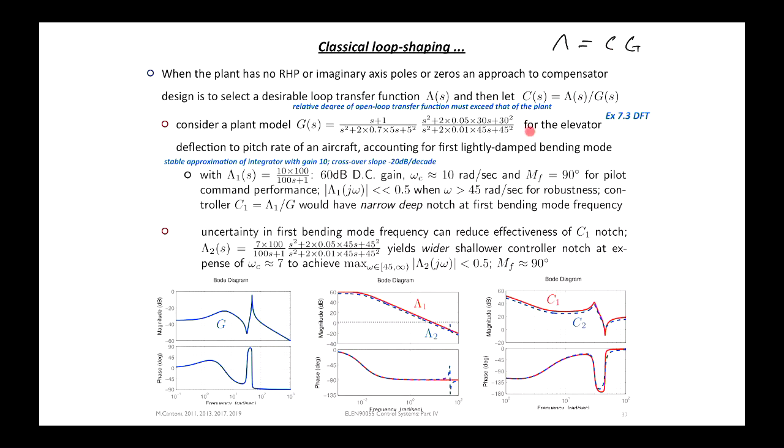Okay, so this example here involves a transfer function for an aircraft where there's some rigid body dynamics with quite good damping, and then some flexible modes. All right, so this is the Bode plot, and you can see that the zero causes this to happen, and then the resonant pole causes that to happen.